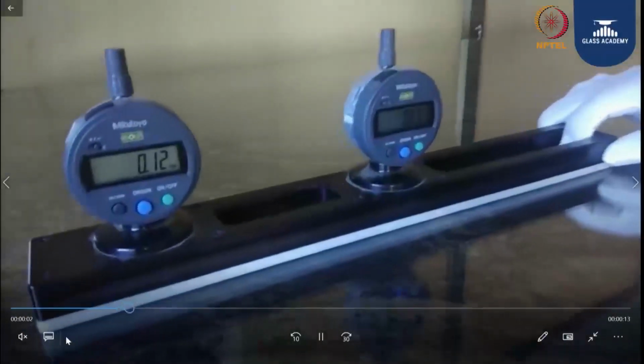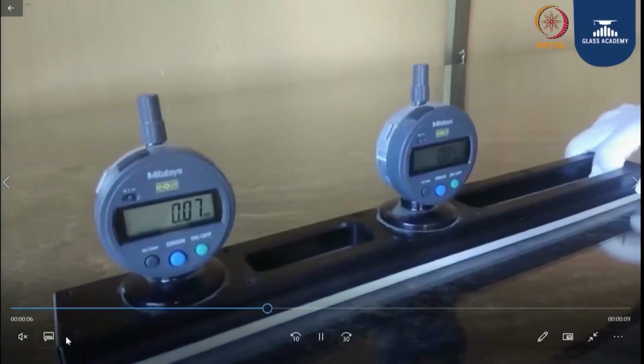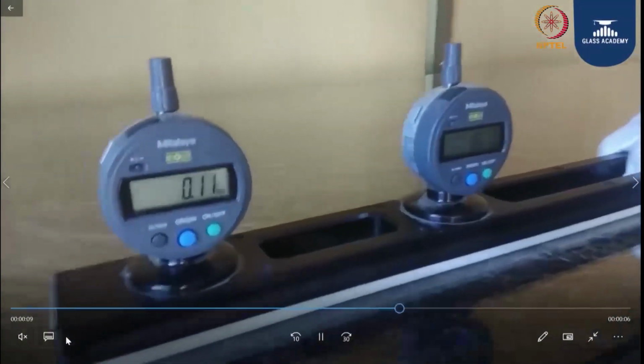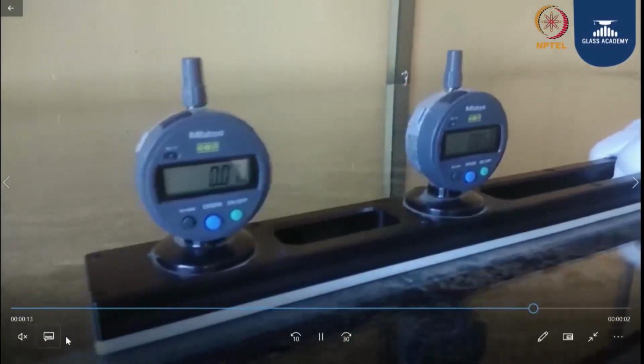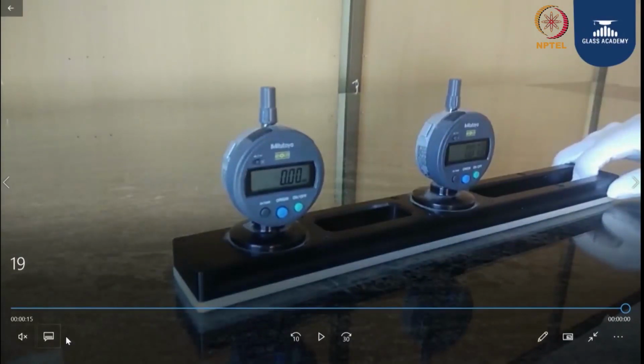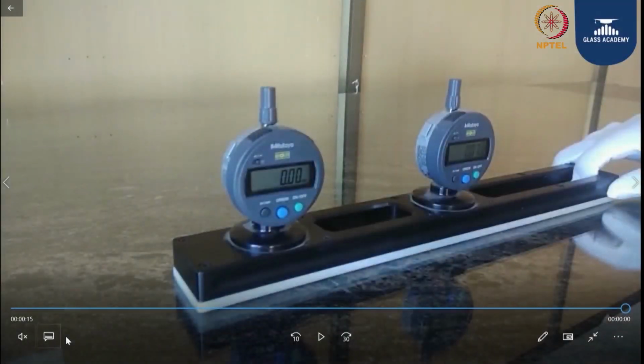If you see, I am taking a glass and I am making sure that as the glass is moving on the roller, the tin side, the bottom surface, will be in contact with the roller. So I need to place the bottom surface on top of the glass, and the measurement of the roller wave should be perpendicular to the direction of the glass. Generally we send the glass width parallel to the furnace. At the time of measuring the roller wave, I should make sure that whichever surface is in contact with the roller I am keeping on the top, and I am using a flatness table to nullify the gravitational force. And with the help of a roller wave gauge, you can find here the roller wave gauge. I am replaying this video here.